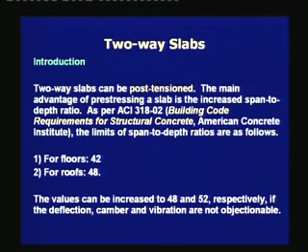Thus, we see that the main advantage of pre-stressing a two-way slab is to increase the span to depth ratio. The span to depth ratio of a pre-stressed slab is much higher compared to a conventional two-way slab.